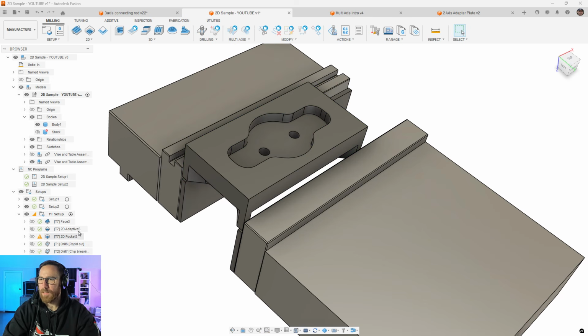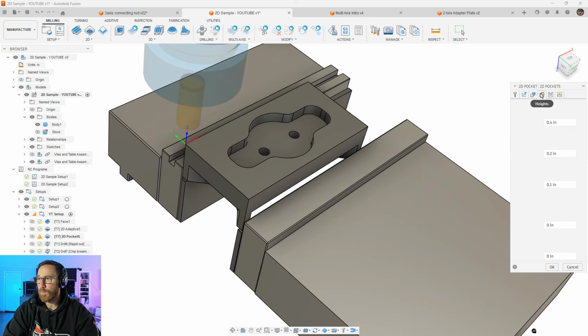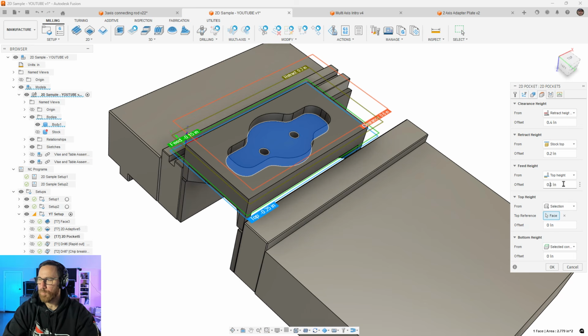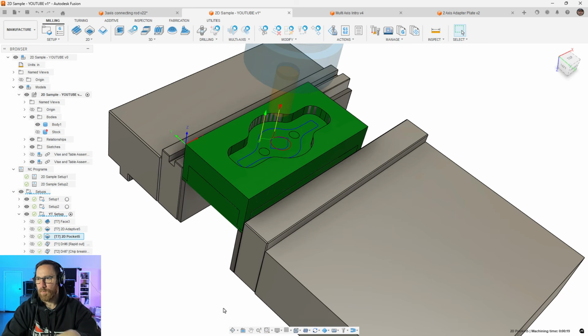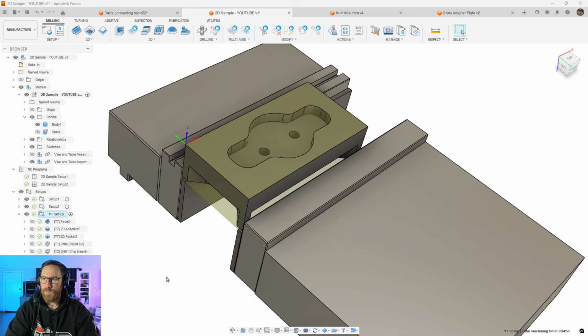But in reality, what you would really want to do is make sure that you've got an appropriate amount of distance for that tool to do its helical entry and that it's not violating any of the other settings. What Fusion will do with warnings is override them. It'll tell you what it's doing, but then it'll choose the safest option based on your settings. And if it's an actual error, there are some errors that will prevent you from actually posting the code.